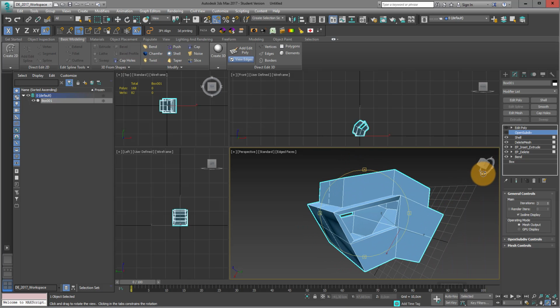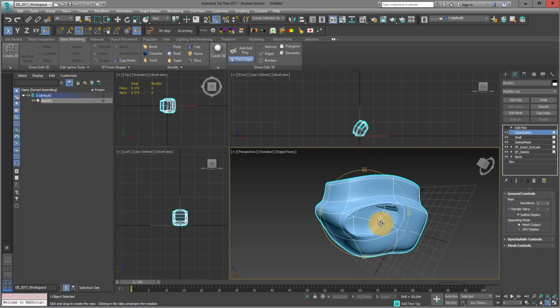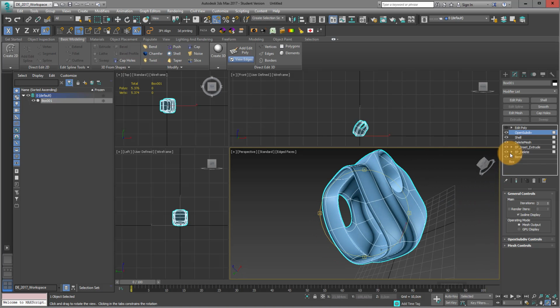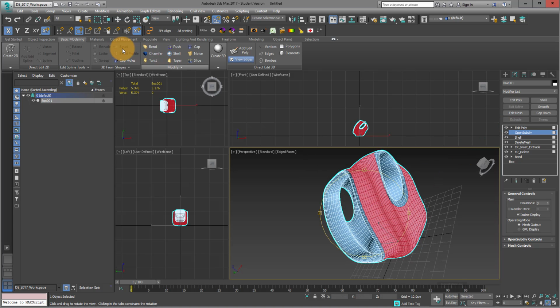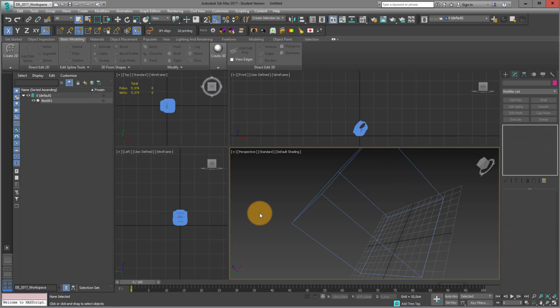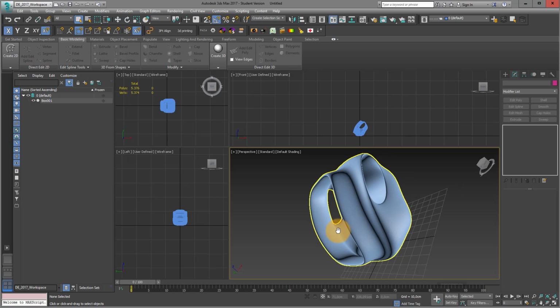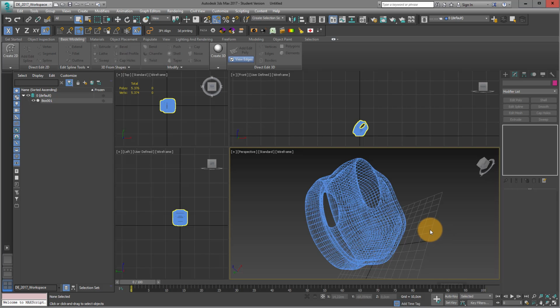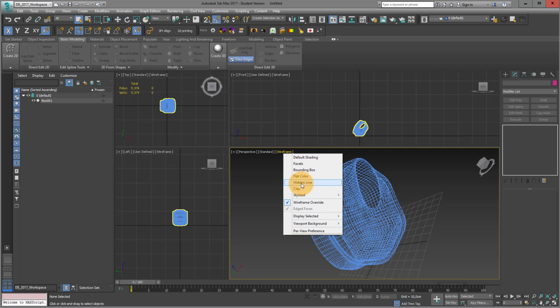And this is another example where you can see how the order of the modifier tab does something. If I deselect my object like this, then I can use my F4 key and I can switch off the edges and I can switch on the edges. I can swap to my wireframe mode. This looks really complex, and also to the other kind of settings.